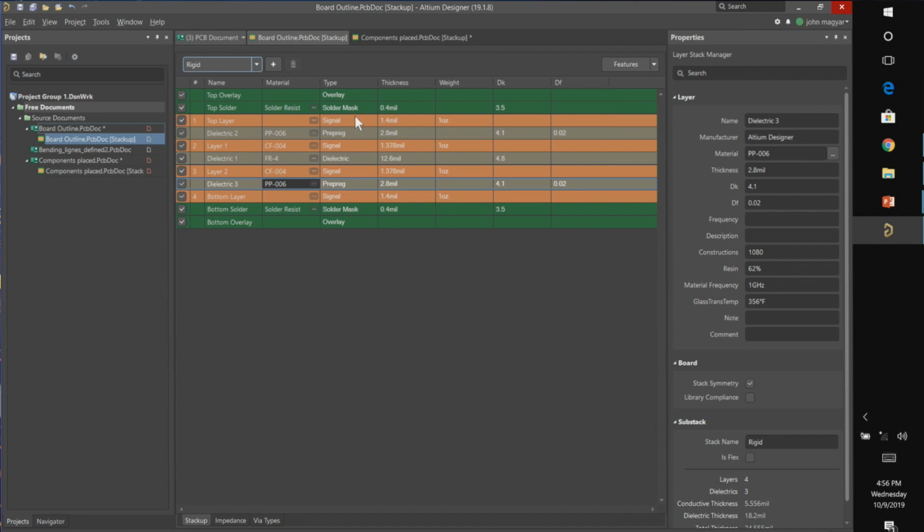You can have like an 8-layer rigid and then like a 4-layer rigid on the other side. It's totally fine, as long as your flex copper goes all the way through. Oh, yeah. Oh, sure. That's what I meant. These would be different things. Right, the dielectrics.